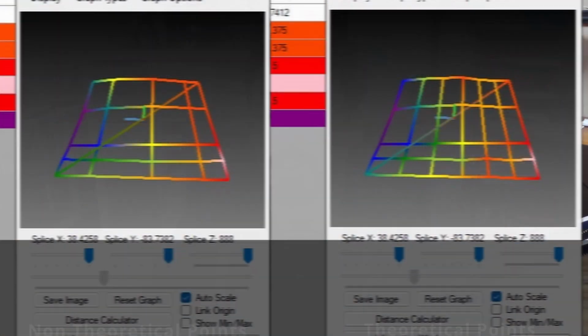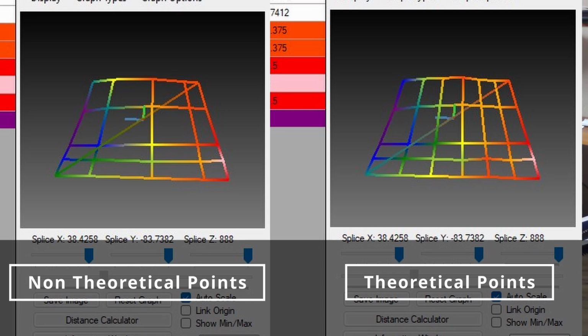When graphing in a mesh format, not all data plotters read meshes the same way. Excel, for instance, assumes and expects each data point to be evenly dispersed. If the mesh data Excel is plotting has a tightly condensed set of data and then a data set spaced further apart, it will plot this data as if it was all spaced evenly, resulting in a poor depiction of the data. Theoretical points is an option that will allow XYZ Mesh to calculate distances between points. This results in a more accurate depiction when exporting to Excel.